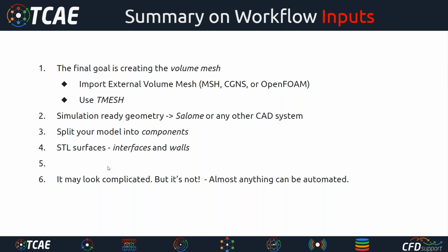It's not difficult to set up the simulation, it's not difficult to run the simulation, it's not difficult to process the simulation and view the results, etc. Everything, but creating the geometry properly in the beginning, we call them inputs. Basically it's the geometry. So to create the geometry properly is typically a bottleneck, because it's very sensitive.